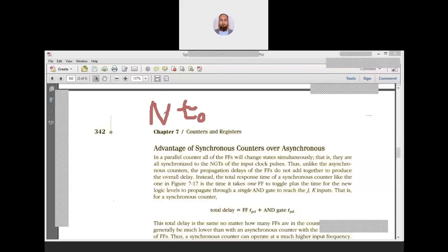If the delays are increasing, we have to increase the time period of the clock, because for the normal operation of the flip flop, the time period of the clock must be greater than all the delays. So when we use a high value of t, the frequency of the clock reduces. This we have discussed already. What happened in the synchronous counters?